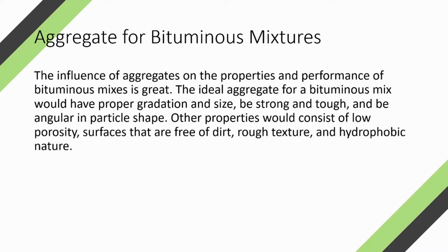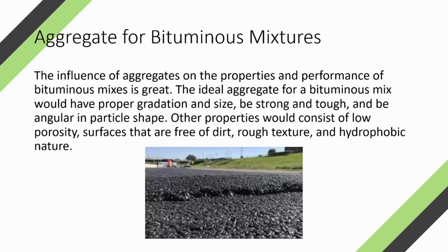So, next, for bituminous mixtures, the influence of aggregates on the properties and performance of bituminous mixes is great. The ideal aggregate for a bituminous mix would have proper gradation and size, strong and tough, and be angular in particle shape. Other properties would consist of low porosity, surfaces that are free of dirt, rough texture, and hydrophobic nature. So, ito yung ating bituminous mix.